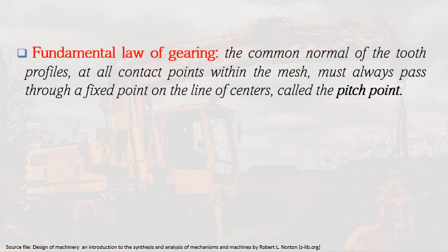Therefore, we can restate the fundamental law of gearing this way: the common normal of the tooth profiles at all contact points within the mesh must always pass through a fixed point on the line of centers called the pitch point. So this mesh should always pass through the pitch point.